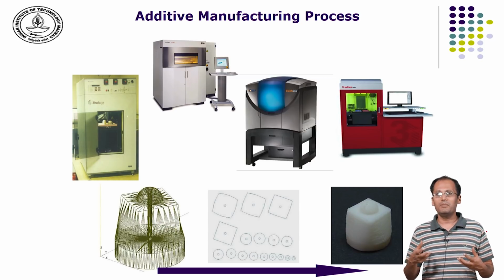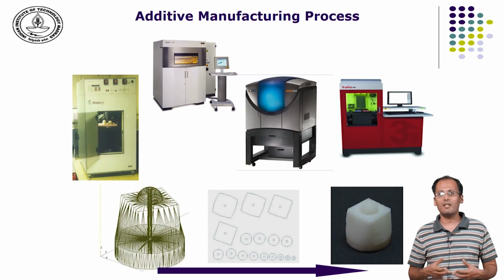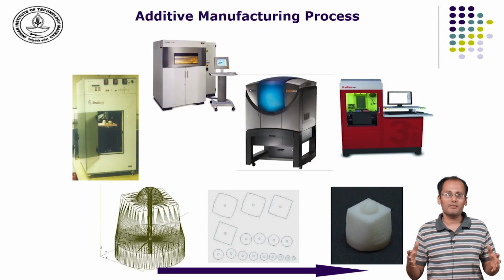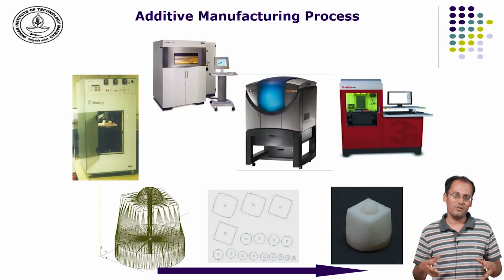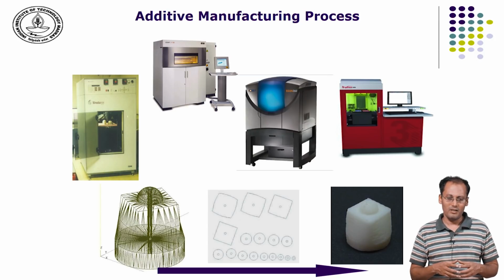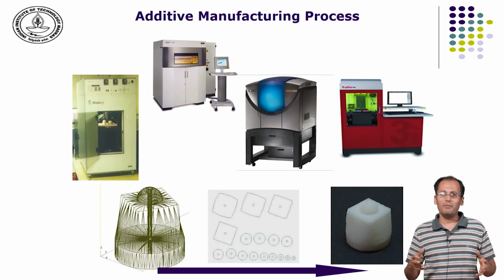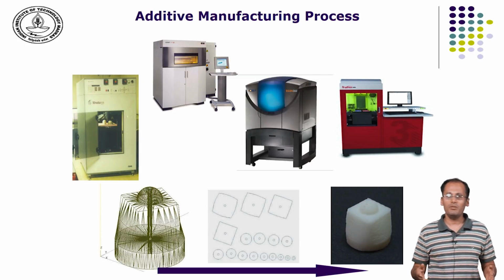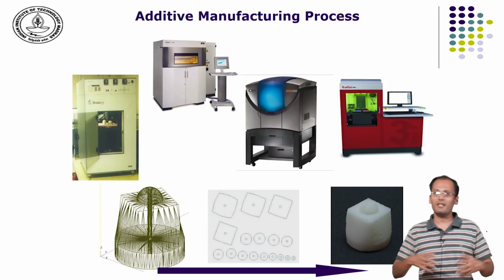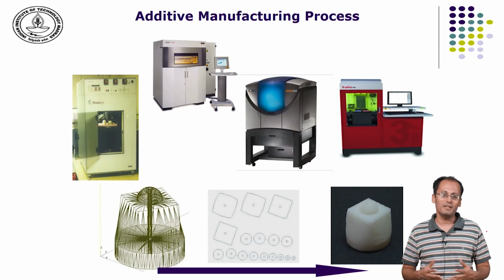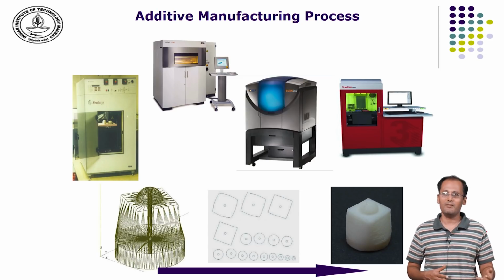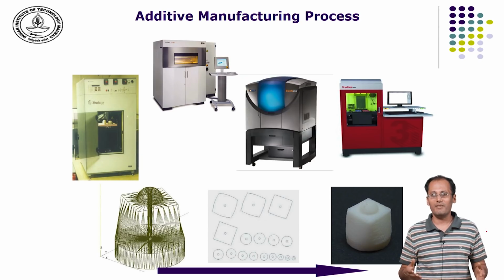Conventionally, we have been building parts from homogeneous material. We take a block of metal or a block of wood and we machine it out. So, it is presumed that the material is homogeneous and isotropic. We have been representing in CAD only the boundaries rather than what is inside. Everything inside the boundary was assumed to be made of the same material. So, as a representation scheme, the CAD models were representing only the surfaces.